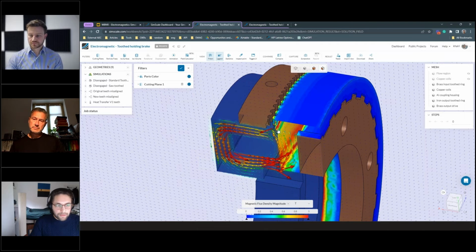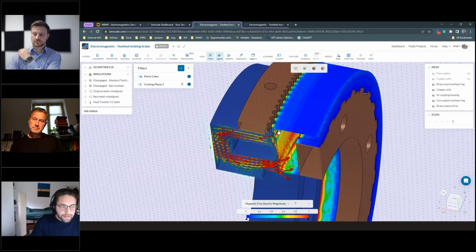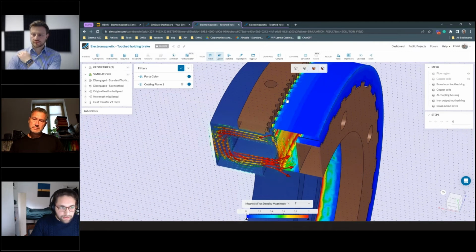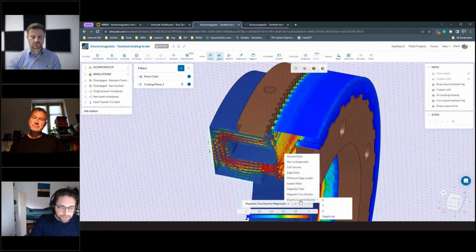around the coil. What we would like to also make sure here and investigate in detail in different applications is that from here we see how the teeth of the armature are magnetized. Now this is set up with a nonlinear magnetic permeability, so we can also investigate any saturation effects that could affect the total force generated and so on. Inside the post processor, of course, you can also investigate the current density. The flux density is what we are looking at the moment, and the magnetic field intensity H.